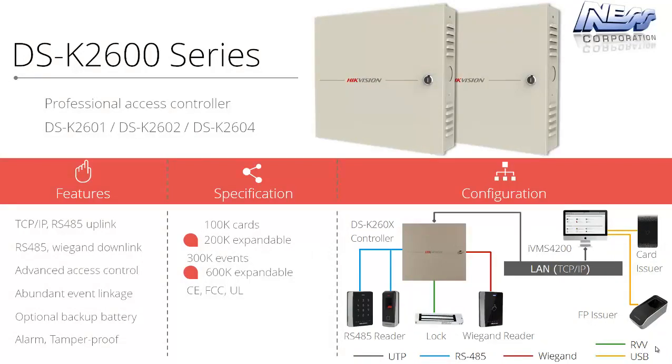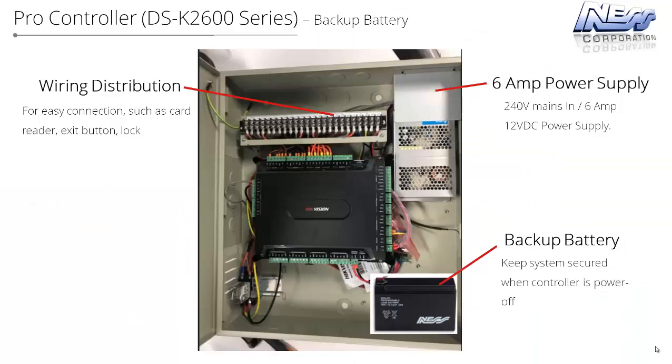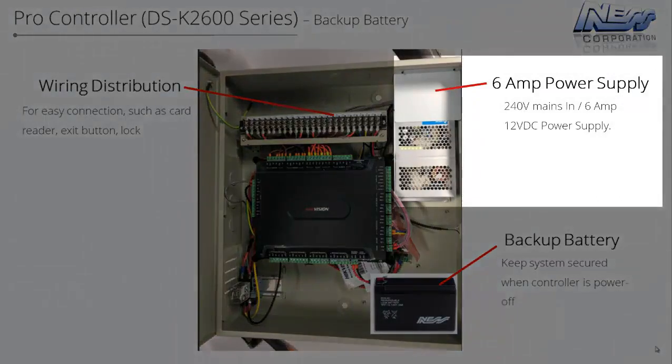They have many other features that you expect in a professional access control system, from multiple access levels, multi-door interlocking, anti-passback, multi-card function, first card presented in the morning function, TCP/IP communication, so it will communicate back to the front-end computer, and the communication data is encrypted to ensure information security. It is a true standalone high security controller that always makes the decision if communication is lost to the front-end computer. It's supplied in a lockable metal cabinet with a 6 amp power supply, and that power supply is large enough to power the controller as well as up to 4 magnetic locks.